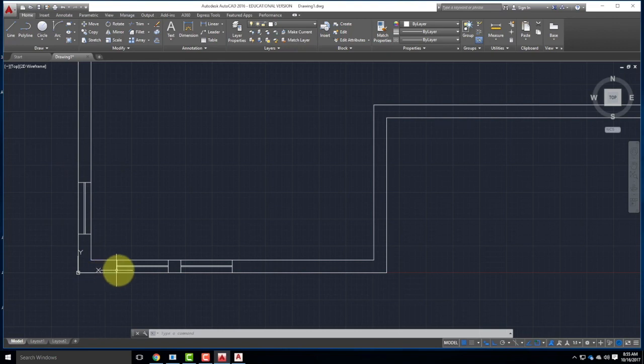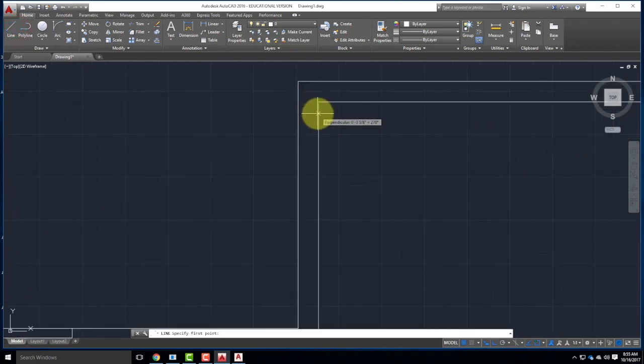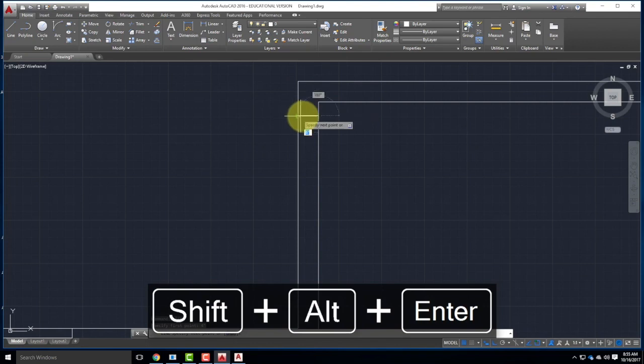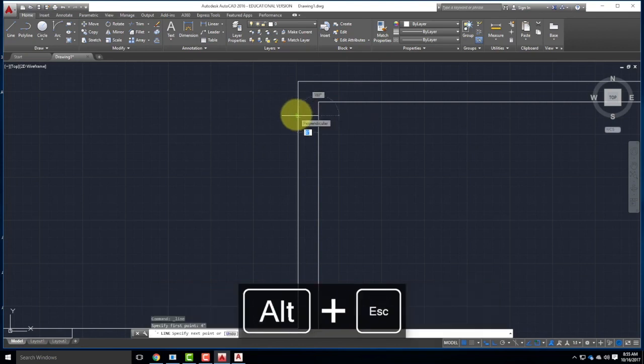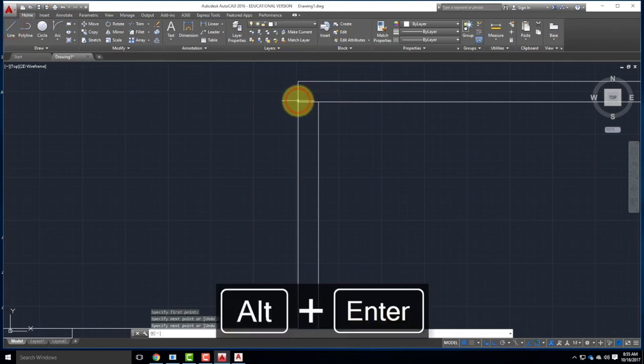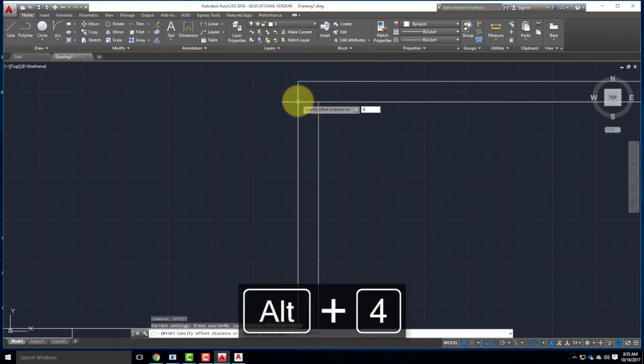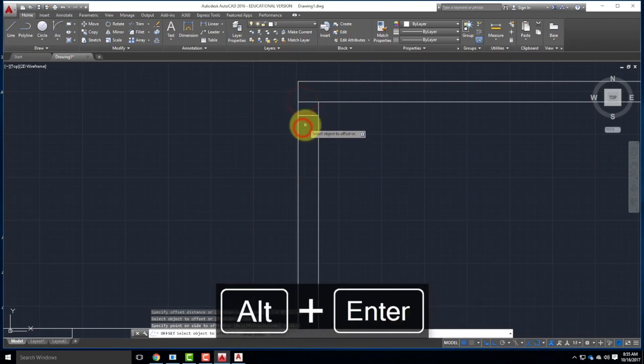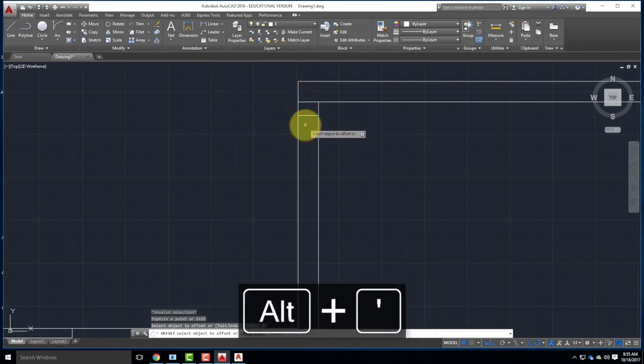You can see a lot of the dimensions. There's a few other dimensions that aren't there, like this door here. I don't know exactly where that door is. I could say it's maybe 4 inches away from the wall. Now, let's say that I want to draw this line at 4 inches from the wall. I could use the same commands we've been doing. I could draw a line there. I could do offset 4 inches, and then offset 3 feet there, for example.